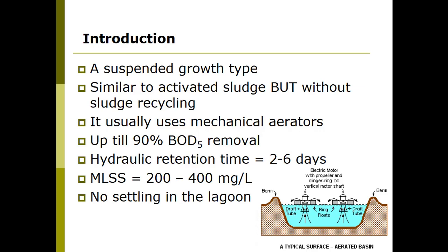BOD removal can come up to 90%, which is very efficient. Hydraulic retention time in these ponds is 2 to 6 days. The mixed liquor suspended solids is only 200 to 400, unlike the activated sludge, which is always around 3,000 to 5,000, because here there is no sludge recycling.